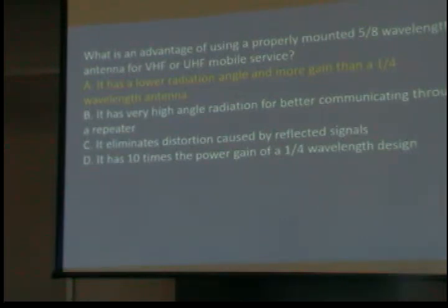But with the quarter wave antenna, the strongest signal goes out at 45 degrees up. Who's going to hear that one? Aircraft, aliens. With the 5/8 wave, that strongest signal is down almost horizontal. So even though I don't have the heavy gain that you would think, I do have a stronger signal there.